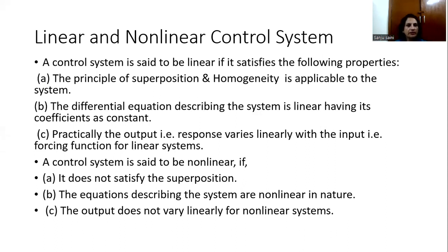If we talk about the electronic components, we are having the saturation. Then we are having the non-linear devices, like in case we are using a transistor or a diode within a particular circuit, they are having the non-linear characteristics. They will make up the system as the non-linear one. So non-linearity is also present in the case of the mechanical circuit, like it is present in terms of the gap between the driver and the driven shaft. Then it is termed as the backlash.